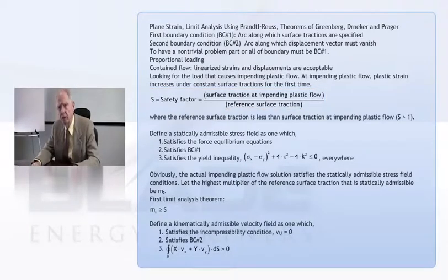You guess some displacements, you toss them into the potential energy, you minimize it, you get a load, and you say, well, for these displacements, this is as good as I can do. Well, okay, here we're going to guess some stresses in this first theorem, and the second theorem is more like the principle of minimum potential energy. So we have to find these stresses.